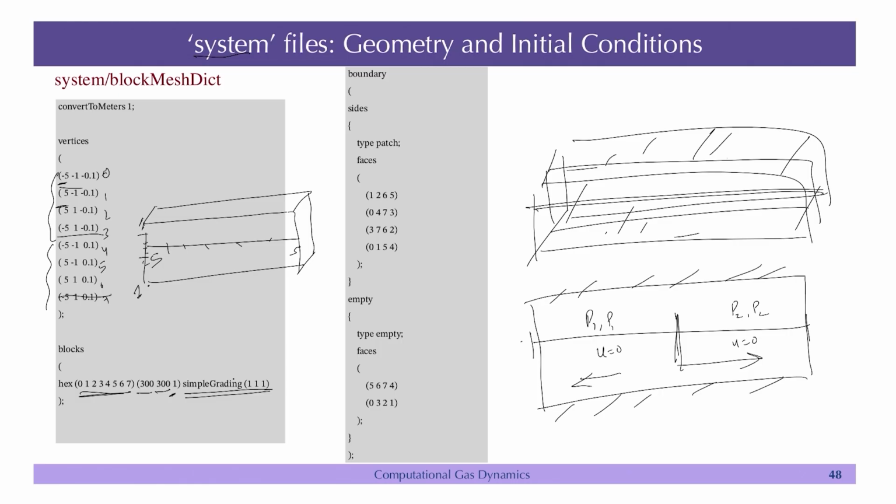So, then you have to define what are the sides, what are the faces that you have, okay, faces are basically the boundaries, okay. So, you have to name all these boundaries so that you can apply the boundary condition in the 0 file, okay.